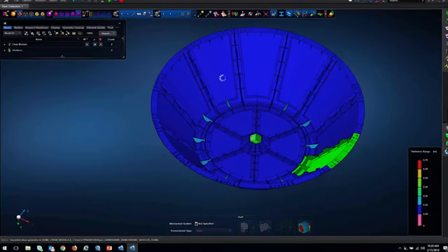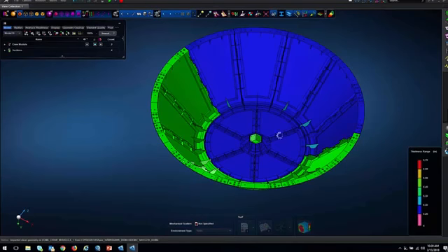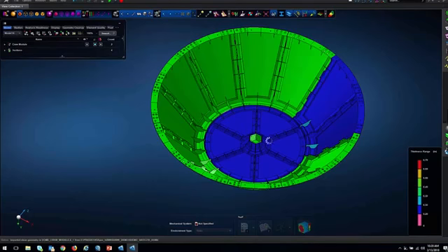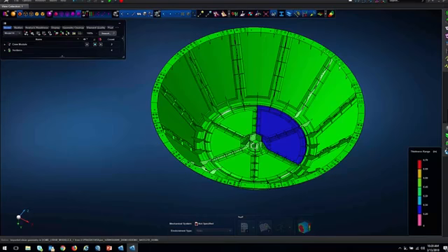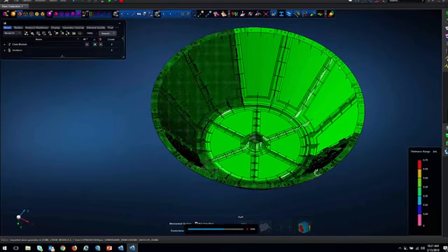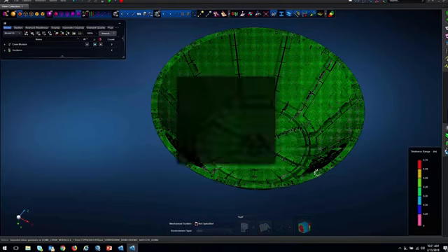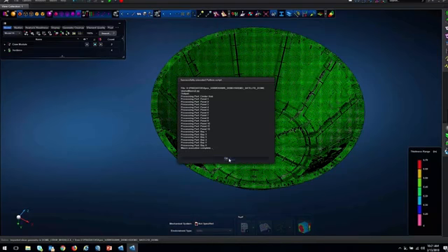And then that macro recorded script was edited to make it generic in nature so that it can be used not necessarily for the identical panel, but also for a similar panel, so that now it runs on a similar panel like this, or the flat panel, also on the web. At the center there is a hub, and now what you are seeing here is that recorded macro, which is edited, run through this model to create the mesh model. And you can see how quick and sweet it can be to create a mesh model like this one using the script.